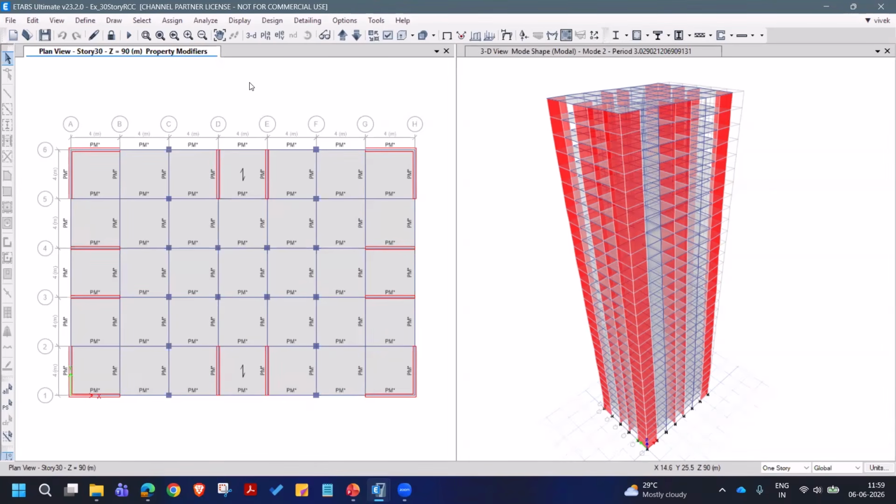In the same way, you can obtain the axial force, and from the other table you can get the displacement, and you can compute the theta value with a quick Excel spreadsheet and see whether it is less than or equal to 0.2. So that can be established. For this building, it is fine. I already checked, not demonstrating.